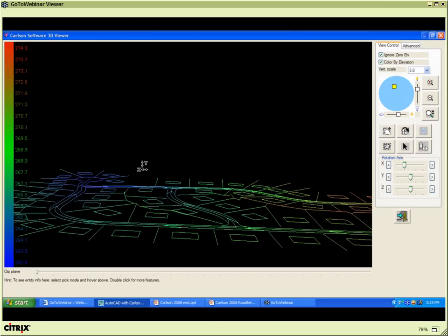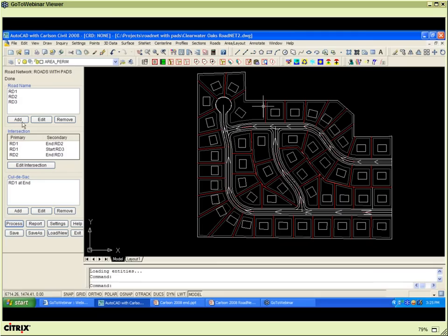Absolutely. Take a first shot at this. You go right from RoadNet and lay out your lots with your center lines. You go over to RoadNet. You elevate your center lines with profiles and templates. Then you elevate your lots and pads, and we can very quickly get a very good sense of what this is going to look like, and of course do a volume calc. And then with SiteNet, you can adjust that, and we'll definitely do a follow-up, Scott, to go in depth on that.